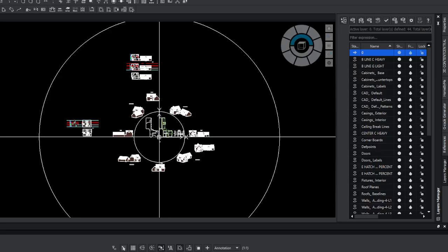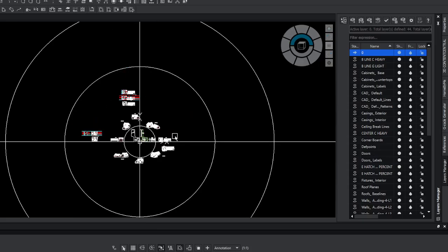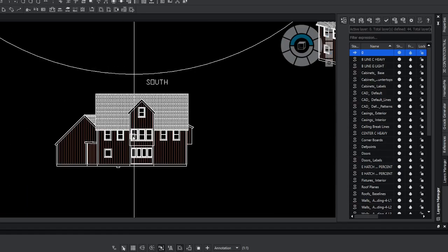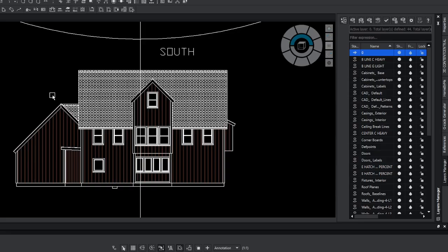So after the model is finished and agreed upon between me and the architect, engineer, or client, then I export it into AutoCAD, and it comes in 1-to-1, and I place it on a bullseye. Basically, this is the 0-0 at the crosshairs, and I go around the compass headings for each part of the building. So you can see that from the export. This has two different layers, or maybe even 3 actually, and it's all scalable.